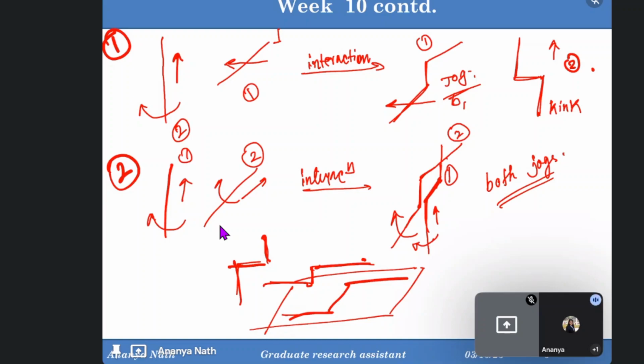It's like they are separated by this now, but still this will move like this, this will move like this, the direction will be same, but there will be a step. Okay, ma'am, now I understood. Yes, ma'am. So the dislocations will still move, but if they have changed the plane, there will be a difficulty in their motion, and their motion direction will be same.